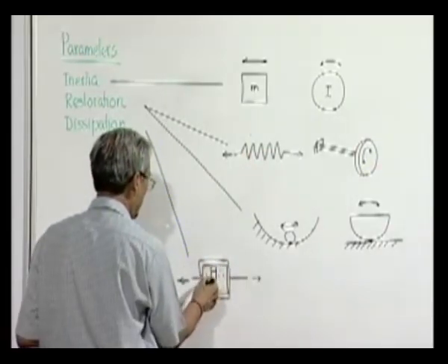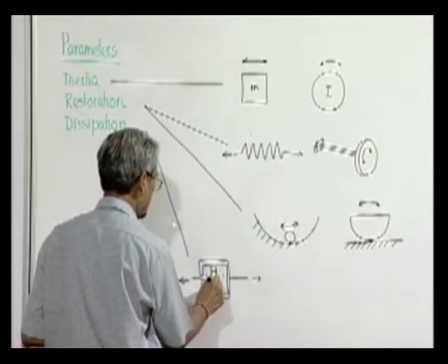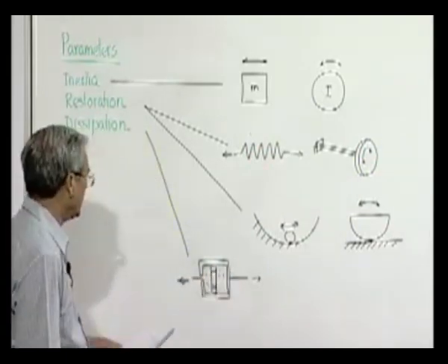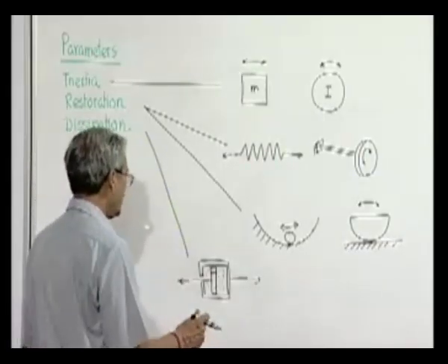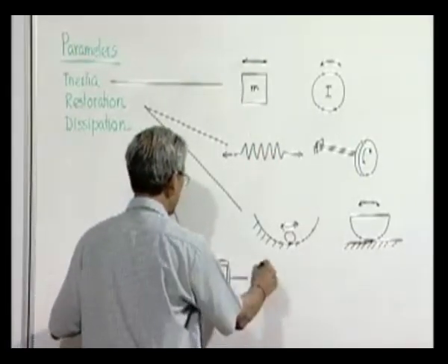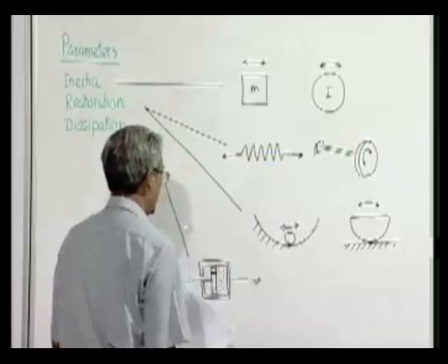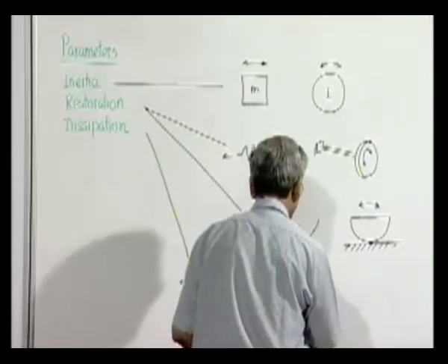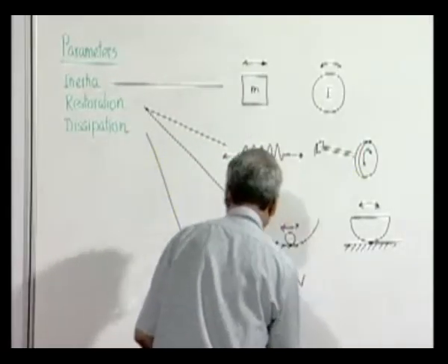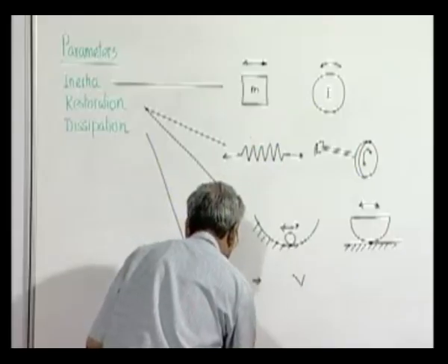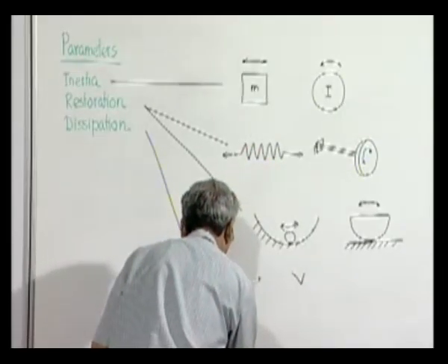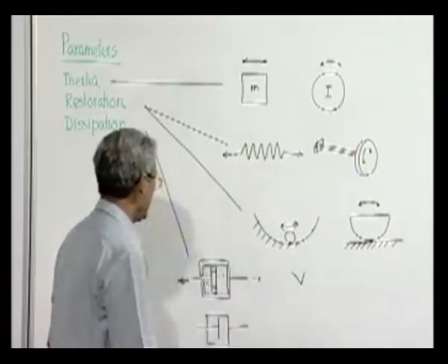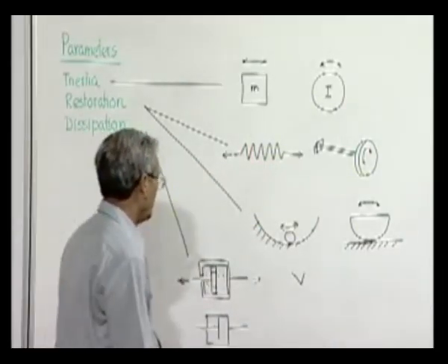On this side the fluid goes through these holes to the other side, and during that process it provides adequate friction, and that is fluid friction, which is proportional to the velocity. This is represented symbolically by this symbol. This is called viscous damping or a dashpot.